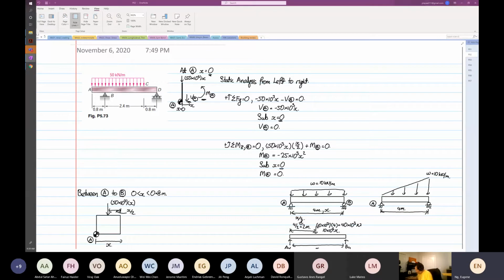So now the equivalent load, in terms of magnitude, is equal to AY plus BY. And we know the equivalent load will act at a very specific distance, right? So let's look at the load. It's a triangle, so it's half base times height.